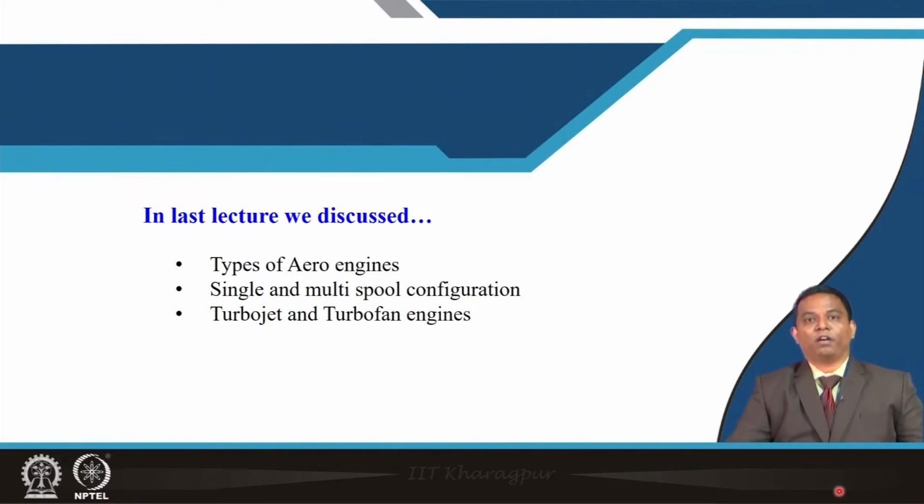You may be aware of the performance map of a compressor, where we discussed that when the compressor is rotating at low speed, there are chances of the front stages getting stalled or going into surge. In the same way, when it is operating at high speed, the rear stages go into surge condition. So in order to meet the requirement for a wider operating range, people are moving to the multi-spool configuration.